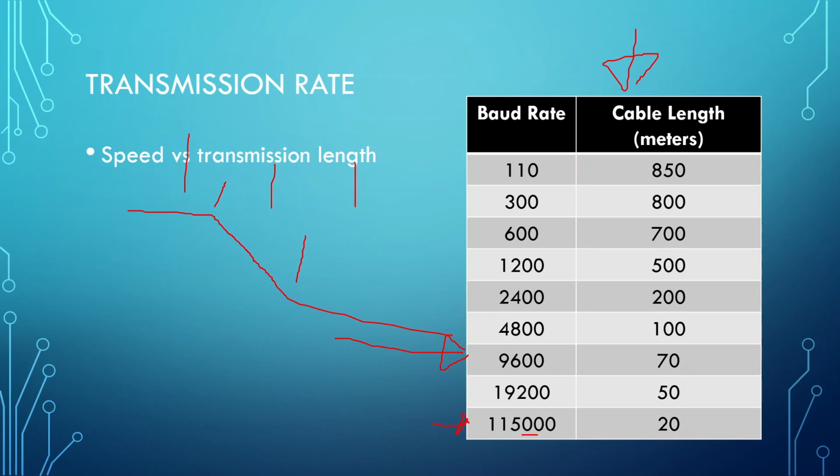So going back to my barcode scanner, if you plug it in and you're getting scrambled data, you probably have the wrong baud rate or other settings set. I actually find it really interesting. To change the settings on a barcode scanner, there's no screen on them, right? You can't just click some buttons. They scan barcodes. In the manual, there are a few pages of barcodes. You're like, oh, you want this baud rate? Scan this barcode. The barcode scanner reads that and goes, oh wait, I should be changing to this. It actually knows those specific barcodes, which I just find really interesting.